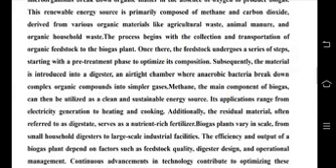Subsequently, the material is introduced into a digester, an airtight chamber where anaerobic bacteria break down complex organic compounds into simpler gases. So a particular part called digester is there. It is nothing else but an airtight chamber where anaerobic bacteria break down complex organic compounds into simpler gases. And methane, the main component of biogas, can then be utilized as a clean and sustainable energy source. Methane will be produced after this anaerobic digestion of the agricultural waste, whatever it is, the initial raw material which we will be providing before the pre-treatment phase.